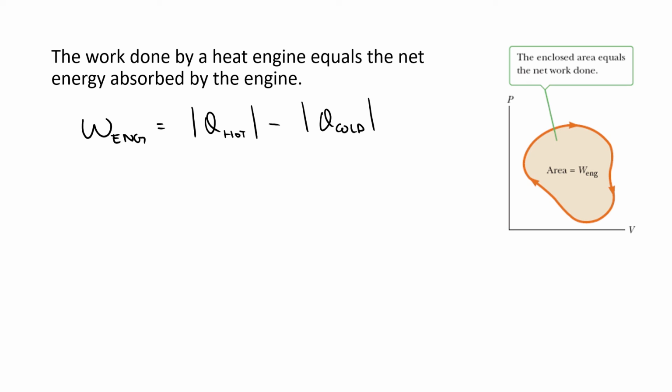It takes in new gas and expands. So that's work done by the gas. It's expanding this piston. And then the cycle repeats again. So we have the cycle that's being created by all engines. And the area that's enclosed inside of that cycle is the amount of work that can be done by the engine.